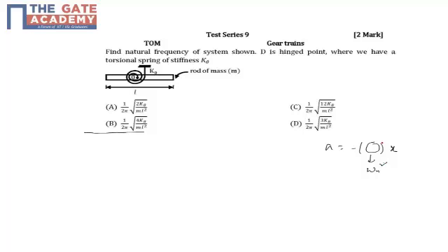So here also, because the angular displacement is a degree of freedom in the angular sense, we will just displace this bar by theta. This is the actual body, and I'm drawing it by one line. This is my mg, with half of the mass acting here and another half acting here.